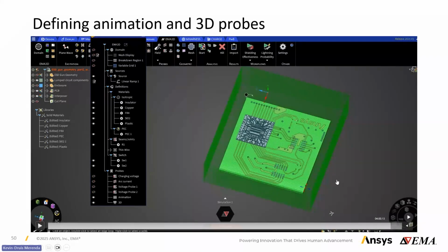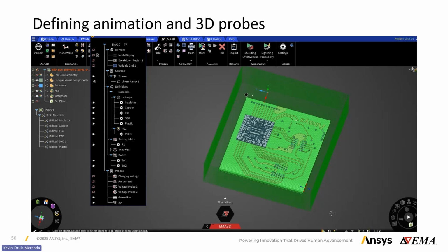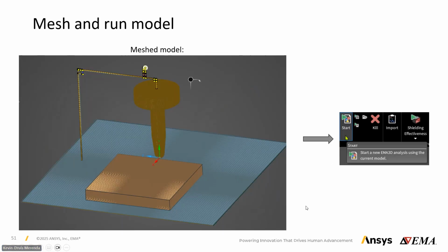You can also sample the spatial grid every cell, every 10 cells or every 100 cells in case you have a very high resolution. That helps you downsize the size of the file significantly. And for the post-processing tools, it might be very important because some of the post-processing techniques and tools out there might not be able to handle terabytes of data to do the post-processing. So just being able to downsample not just in time, but also in space is pretty important.